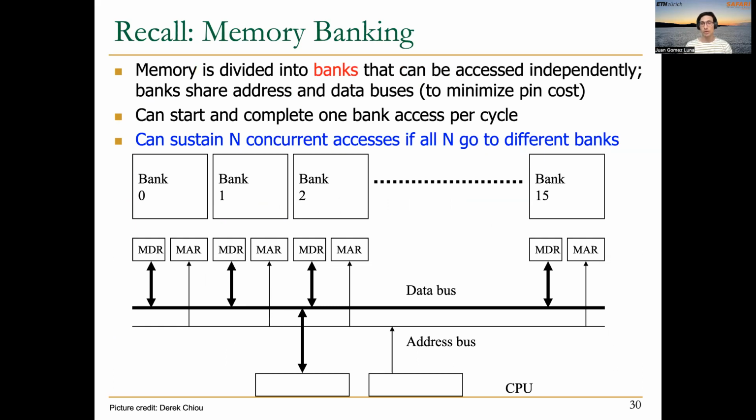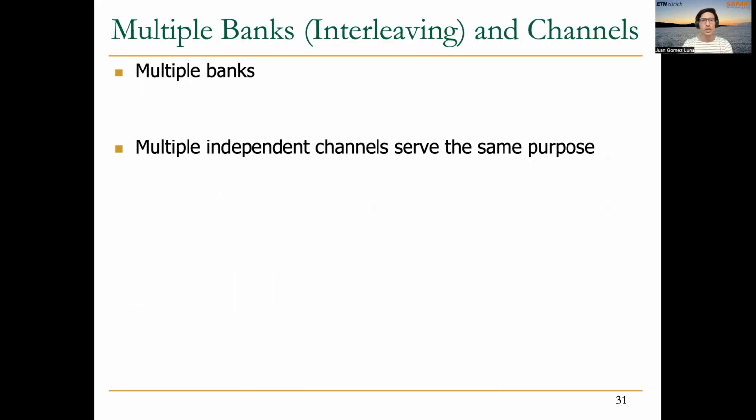Basically, what we have in memories, in all kinds of systems, and in particular in parallel systems like GPUs, are banked memories or interleaved memories that divide the entire memory space into different banks that can be accessed simultaneously. This way, we can overlap the access latency, or the initial latency of opening rows in different banks. We are going to see what the positive effects are in the GPU in this case.